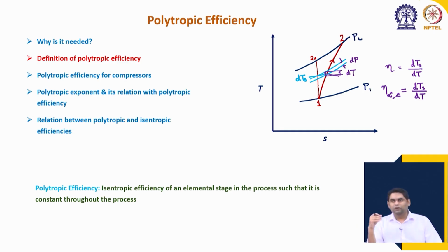So, for turbines which are manufactured in the same place using the same method, the polytropic efficiencies will remain constant, and we can have as many stages as necessary, still the polytropic efficiency will remain constant. So, this is constant. Now the definition should be clear.